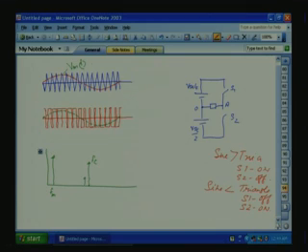then sidebands, FC plus 2 and FC minus 2. Okay. Then you have at 2FC the sidebands, that is 2FC plus 1 and 2FC minus 1. This way the harmonics go. Again it will repeat the same at 3FC and 4FC, where you will have the sidebands. So the harmonic amplitudes, if you see here, will decrease like this.